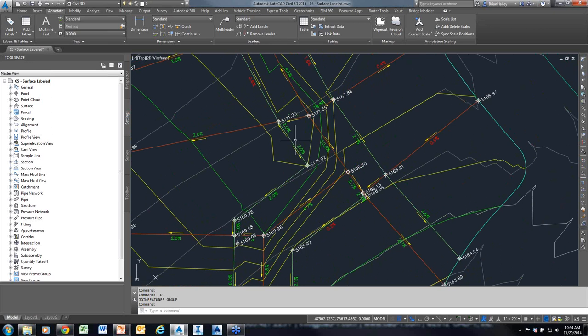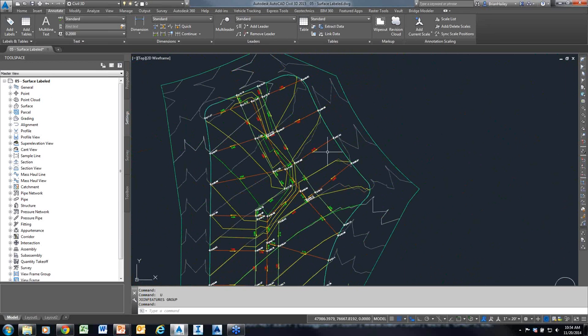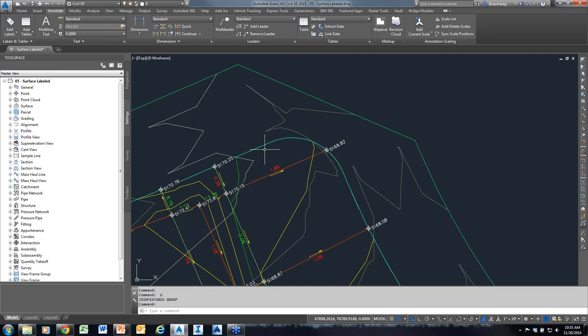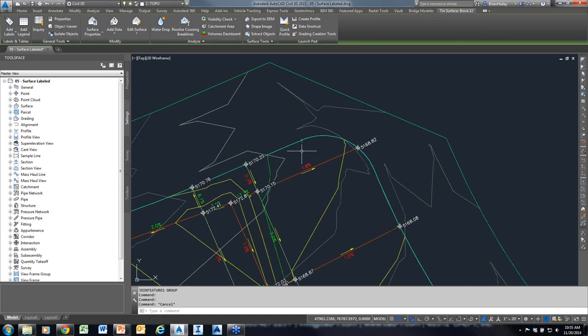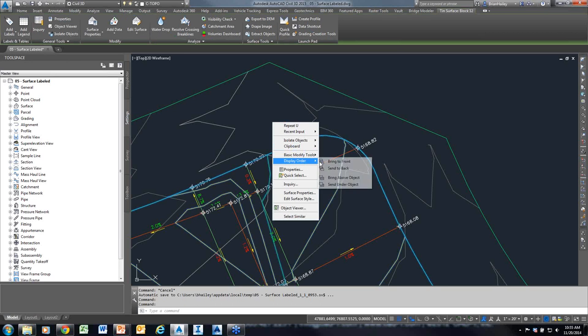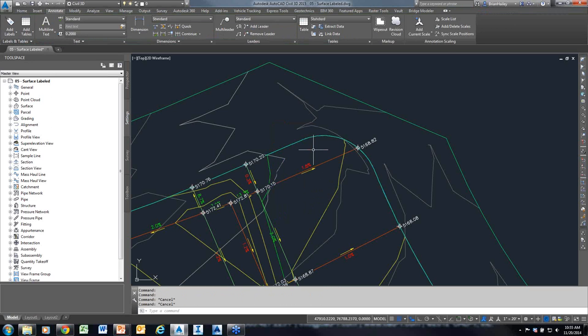Some of the other tools that we have. I can create what's known as a stepped offset. This command's pretty cool. I want to create a stepped offset, so wait a minute. I want to grab that feature line. Oh, I grabbed the surface again. The surface is actually showing a border, and the border is actually on top of the feature line I want to grab. This happens all the time in CAD, right? We grab it, we right-click, display order, send to back, or type it, or whatever you want. In this case, I'm going to show you a cool little tip. So as I mouse over, actually I've got my highlighting turned off for some reason.